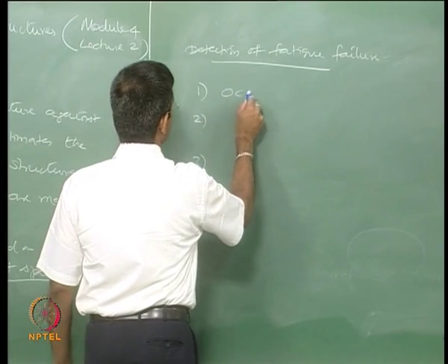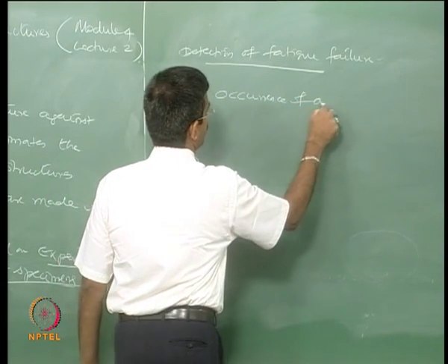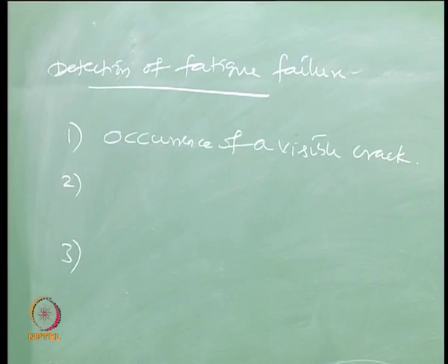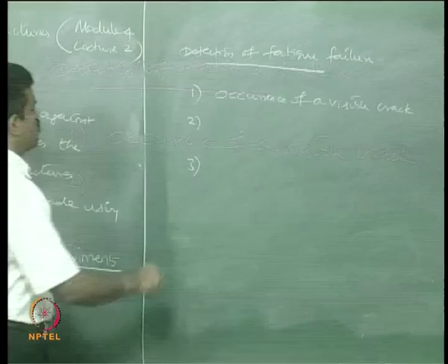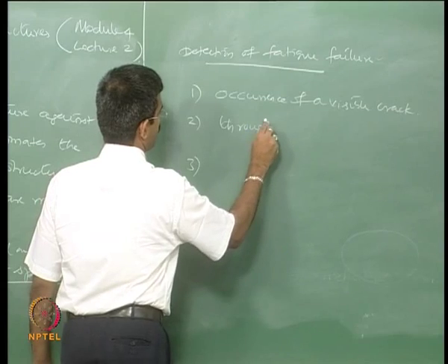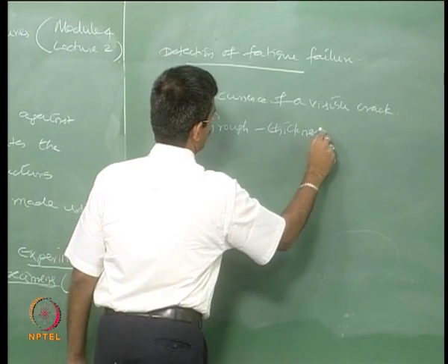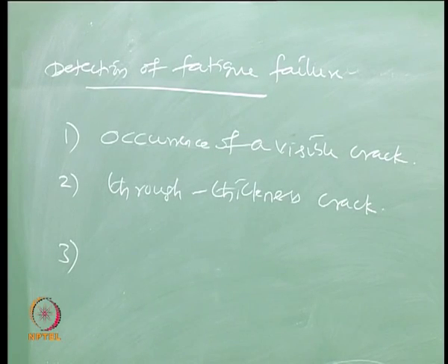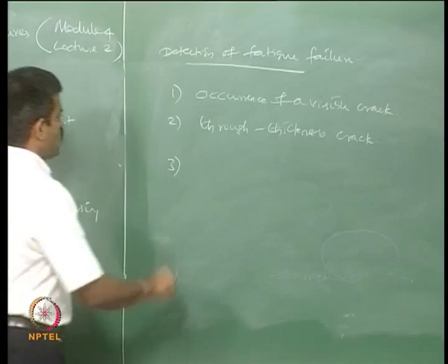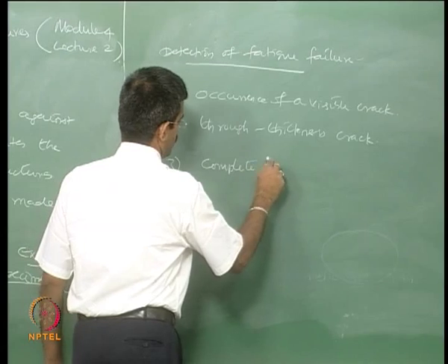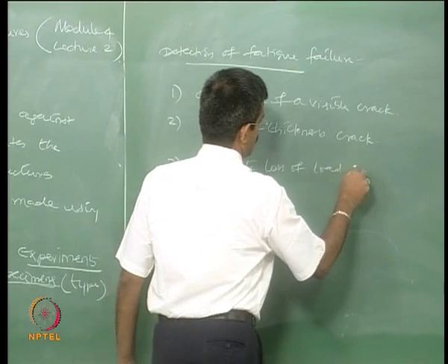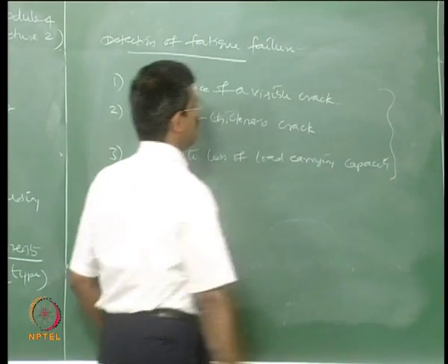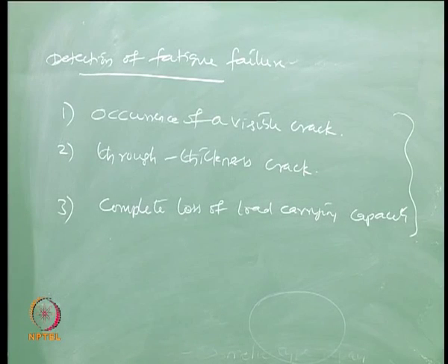When you notice an occurrence of a visible crack, or if you notice a through thickness crack, or if you notice a complete loss of load carrying capacity, then you can infer that the material or the member or the structure has failed by fatigue.